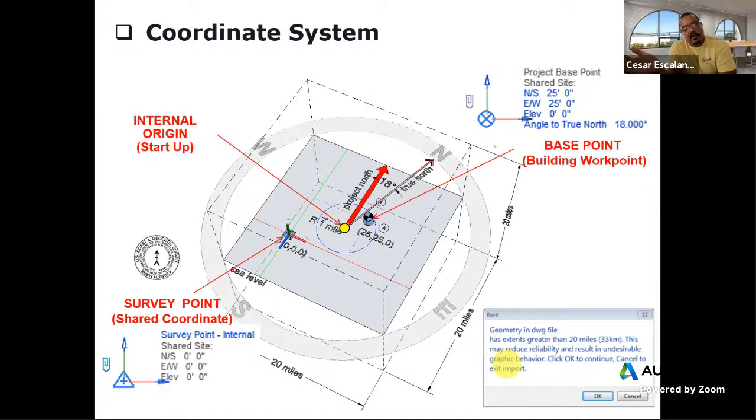And then true north is the orientation associated with the geodesical location of the sun, and is usually aligned with the North Pole. The declination between true north and project north is information we will typically find in our surveys, or information that civils should provide to us. And when we start a project, both project north and true north are aligned.